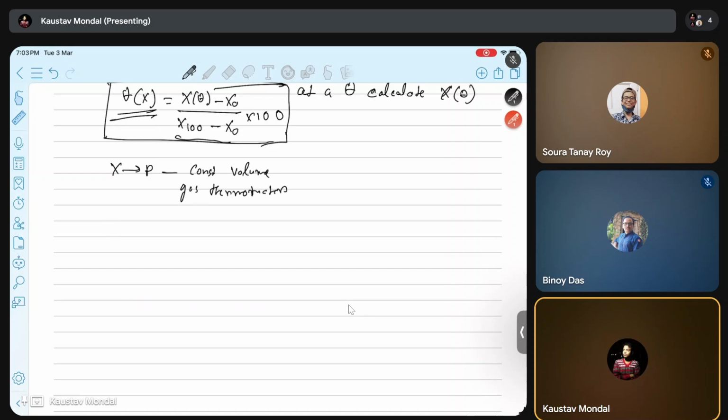That instrument measures the pressure of the gas as a thermometric quantity, and from there, by using this relation, T = 273.16 times P by P_ref, where P_ref is the pressure at some reference point, and P is the pressure at that particular temperature theta.